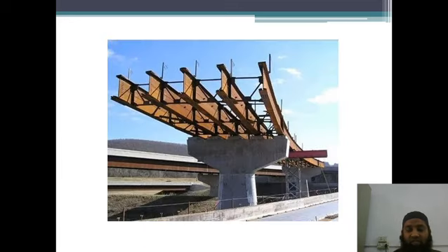You can see here these plate girders have been placed over these bridges, and though they are concrete bridges at the bottom, these plate girders are provided. You can see there are 5 plate girders, and these plate girders are connected internally. Now over this a railway line runs, or a highway runs over it. So basically we have provided this to avoid obstruction at the bottom.